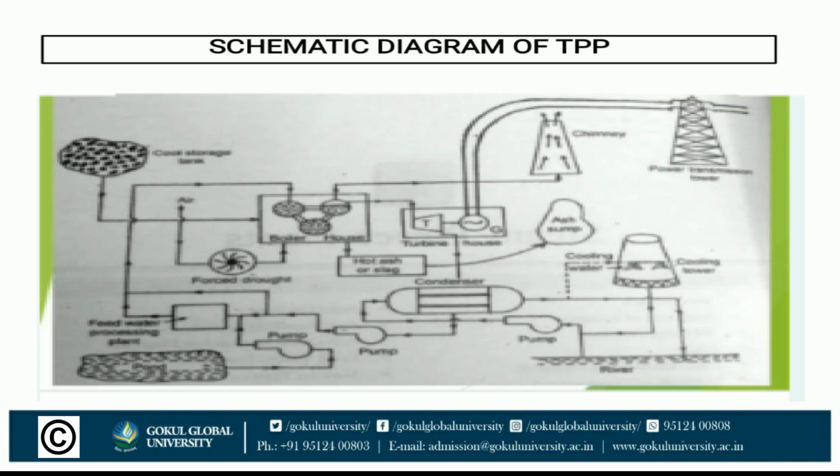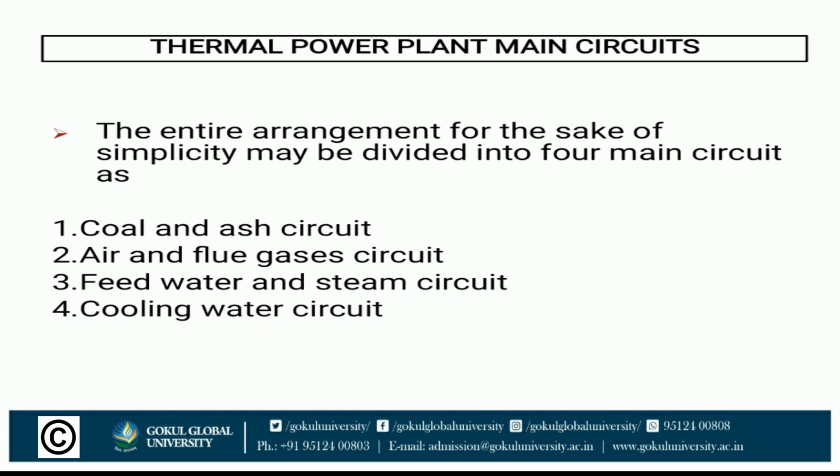When the cooling water coming out of the condenser is cooled again and supplied to the condenser, the system is called a closed system. When the water coming out from the condenser is discharged directly to the downstream side of the river, the system is called an open system.